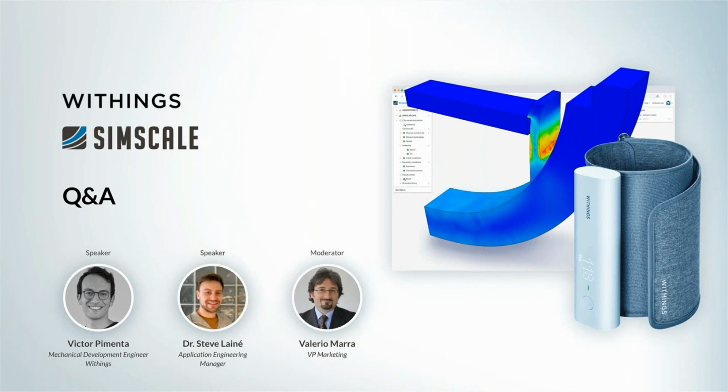So there was some overlap and some stress concentration over the round corner at the base of the clip. And by setting a correct penalty coefficient, we could predict this ahead of production and prototyping. So as a rule of thumb, let's say about 50 times the Young modulus of the softer material, or the average of the Young modulus of the materials involved.